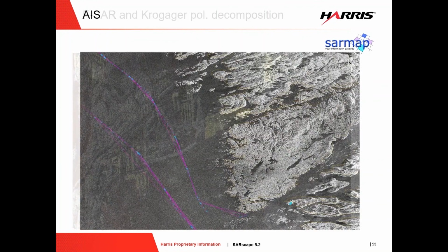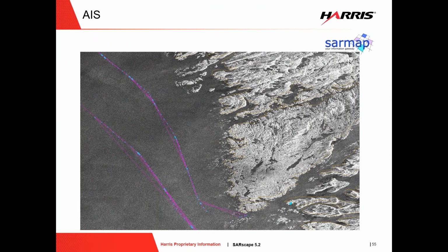And here, another example, again, entering a different type of applications, not the land applications we are used to looking at with SARscape. We are starting to include something specific for marine applications. Here we see a Sentinel-1 data set over Greenland covering a large area, and in another large area we have a lot of ships. So if we obtain, for the same time of acquisition, for a period around the acquisition of Sentinel-1 data, transponder data from exactEarth, I think in this case, we have the location of ships who are transmitting with their transponder, and we have the path of these ships, the route of these ships.